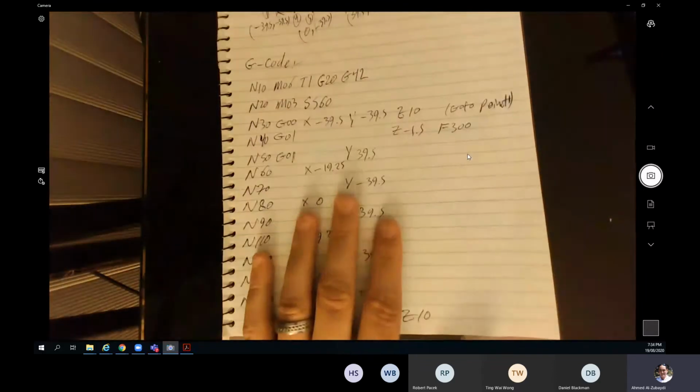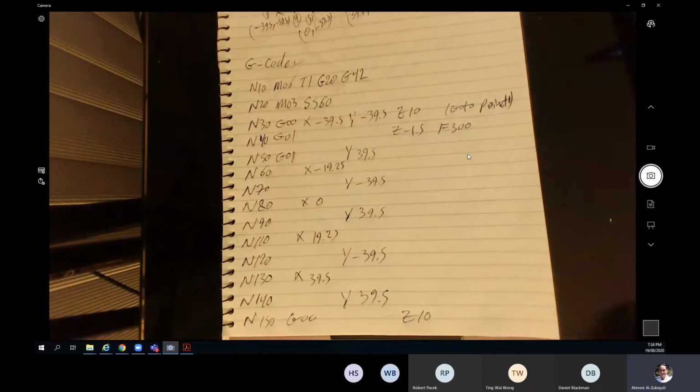Now, the same code, if you're going to type it, you can copy and paste it to the operation number 1 in the setup number 2. So let's see what we'll have on the next page. Just remember, we just reduced the thickness of the part from 30 millimeters to 28.5. We removed 1.5 millimeters. Is that your rough cut? Well, it's up to you to make it a rough cut or a finishing cut, because we didn't talk about the quality of the surface we would like to have at the end. I don't want you to extend the work on yourself by saying, well, actually 1.5 can be done as a finishing cut, by the way.